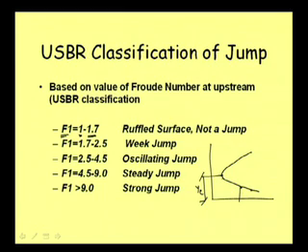And when we are just coming very near to this particular point, when our depth y1 is at yc, the Froude number is equal to 1. Now, when it is just slightly less than yc, say y1, then the Froude number is just a little higher than 1.